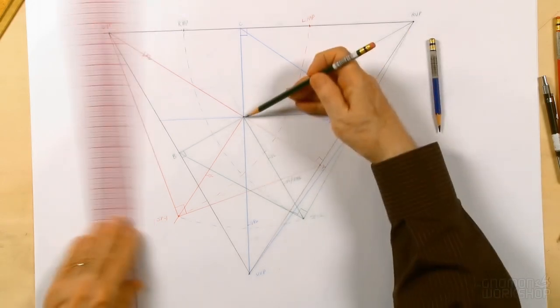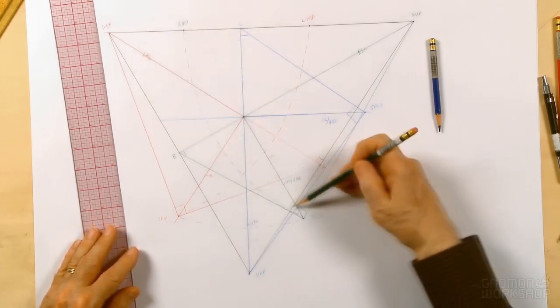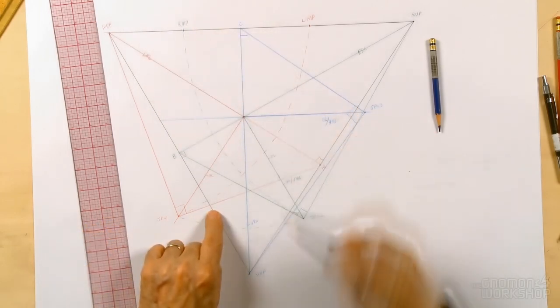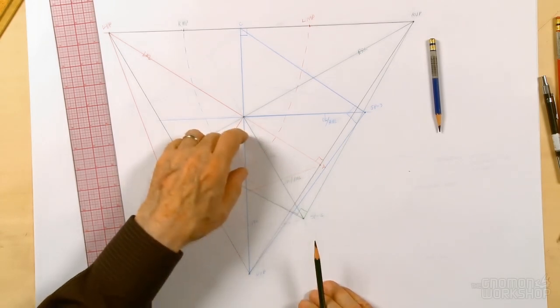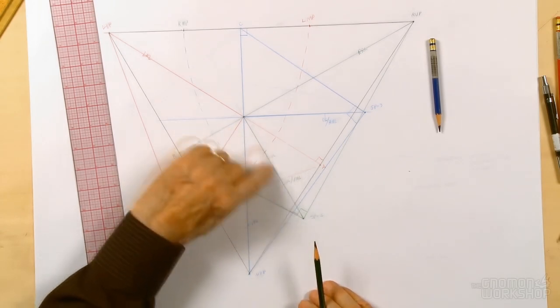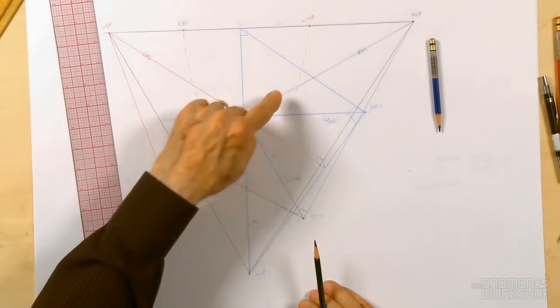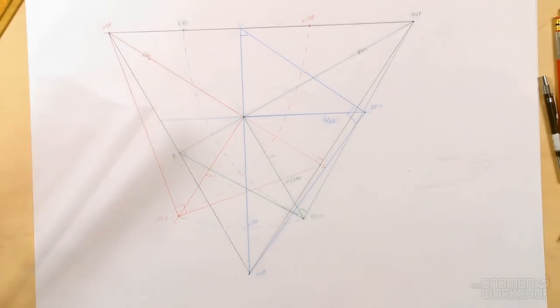Here we have the same thing again. We have a measuring line and what we call a horizon here, and an intervening line in there that is at a different angle than these two lines. So the intervening line will receive the foreshortened dimensions from the measuring line. So here's the measuring line. We will transfer foreshortened dimensions to that green line there for the width, and also over here on this side for the red.